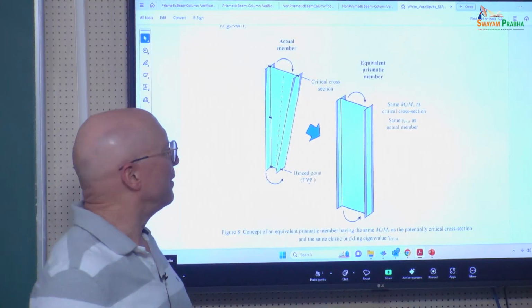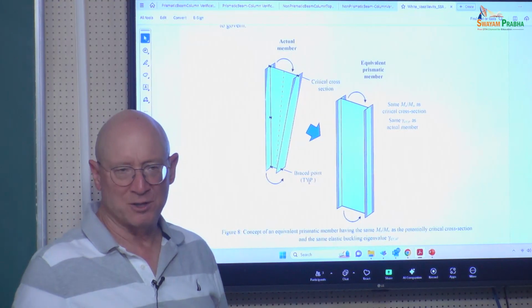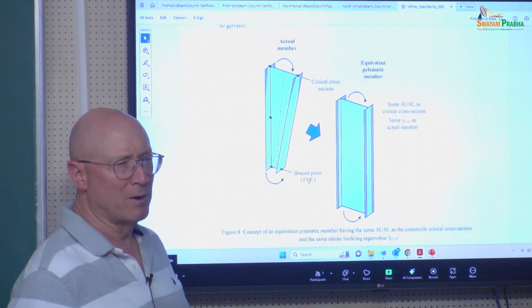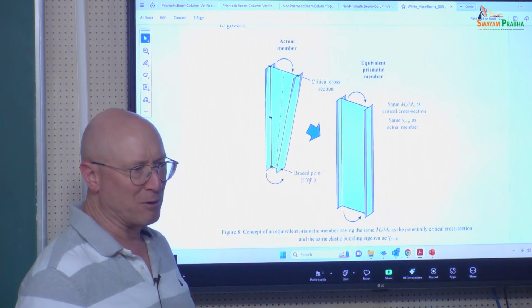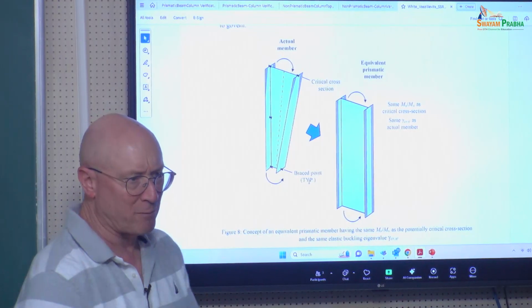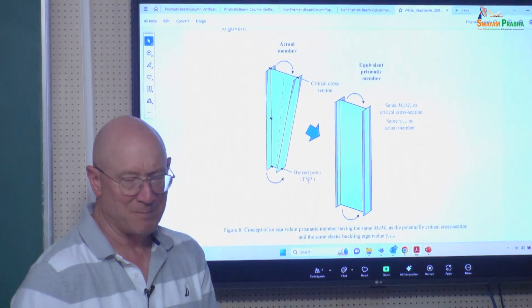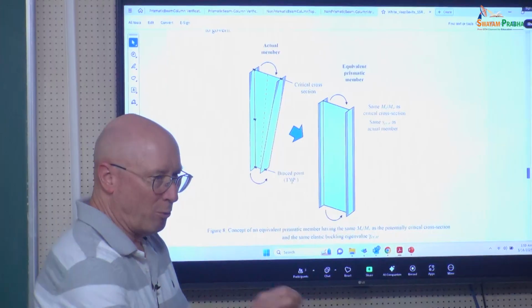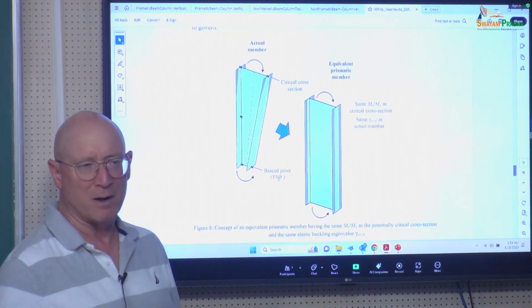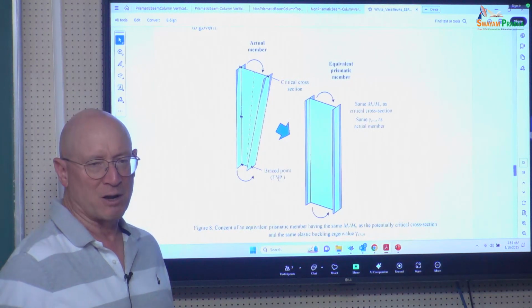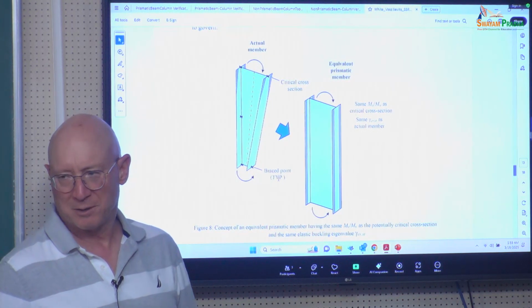Now, again, in Consteel, we're using a rule where we're basically looking at the ratio of MU to MW for all the different cross sections, and we look at whichever one is largest, right? And we're going to take that as a critical cross section, move it forward, and that does a pretty good job of capturing the one that's going to be the largest.